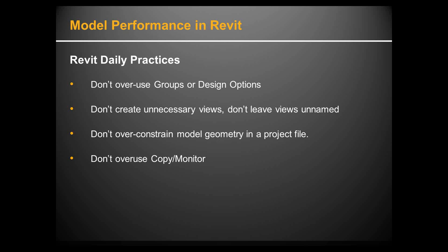What is it? Copy Monitor. Copy Monitor is another great tool. Typically, I see it used for levels and grids, and maybe a little more than that, but don't overuse it. The more you copy monitor, the more Revit's calculating and doing stuff in the background.